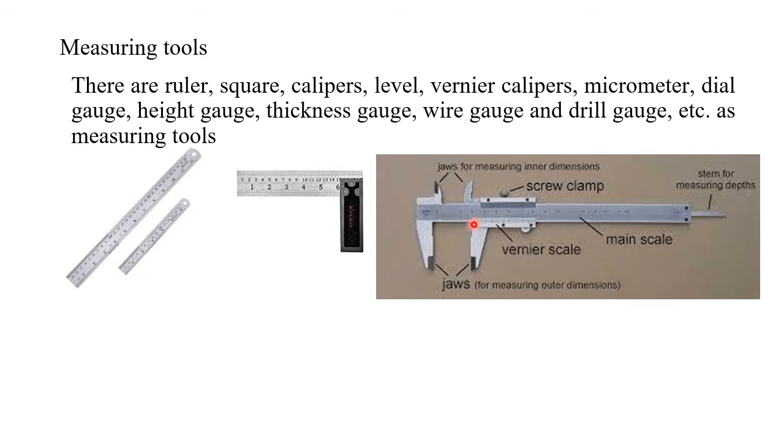You will count these small pieces. So for example, if the number of the vernier which meets with a number of the main scale is 7, then you will have the millimeters point 7, according to the scale of the vernier.